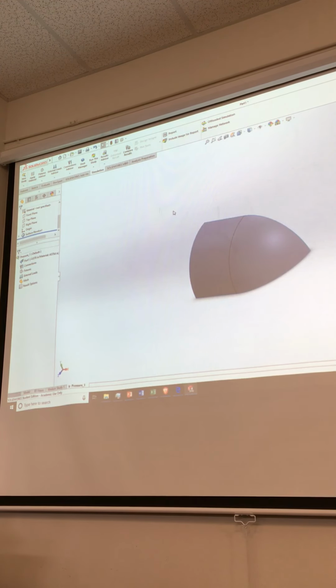It's constant. Most of the time we do use thin. Mostly this way certainly will agree with our numerical analysis, because our numerical analysis will assume a thin shell unless we wanna go do a thick shell analysis. Now, you can use thick and go check it with a thick shell hand analysis. Or you can use the thin shell assumption and go check it with a thin shell analysis.